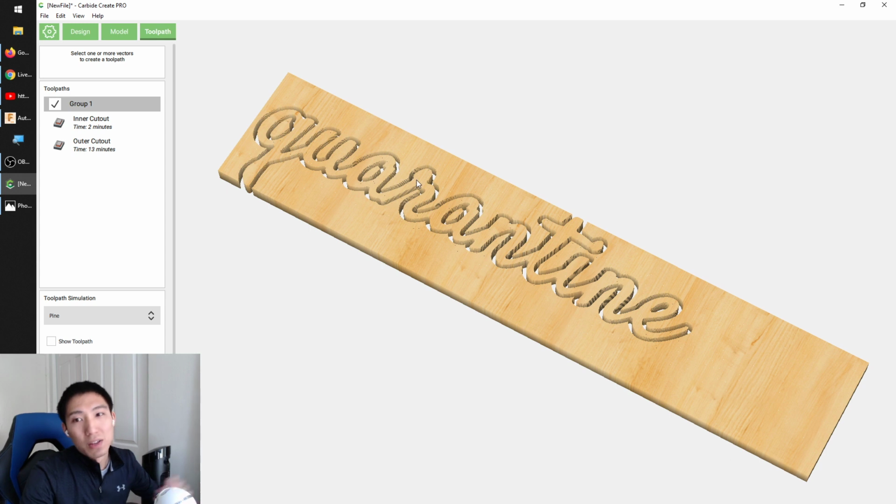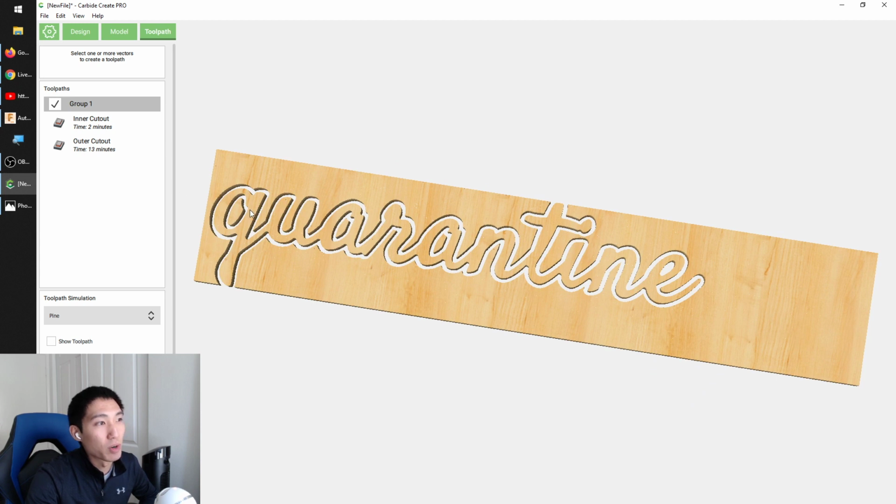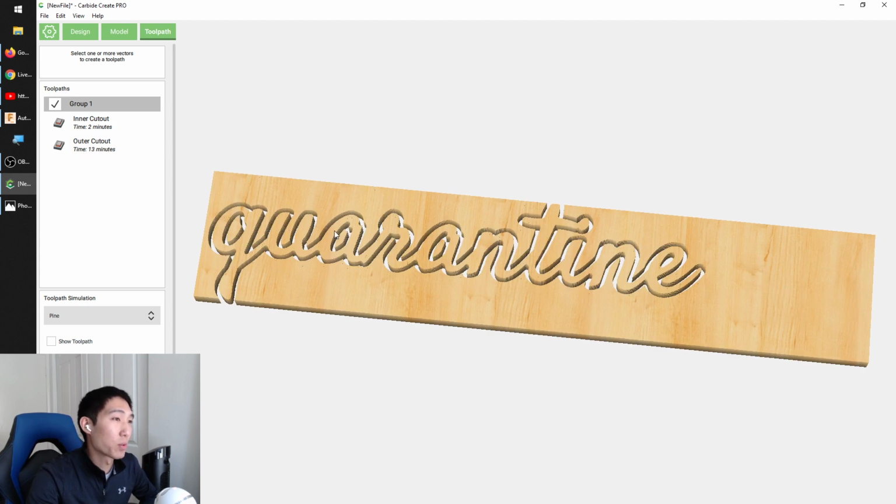Perfectly adequate. When I cut out my sign, I used double-sided tape underneath it, so I just put a large 1-inch wide strip underneath everything. When I cut through the wood, I pulled up some of the adhesive, I gummed it up, and I had to spend a little bit of time sanding away the sawdust that got mixed with the adhesive and smeared across the outer edges of the wood. If you're using a larger cutter, not as big a deal. Down cutting end mill, way better.